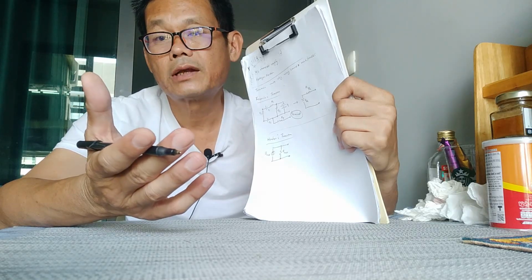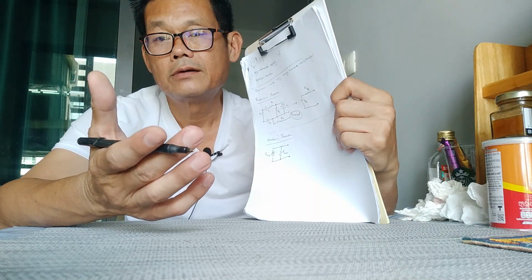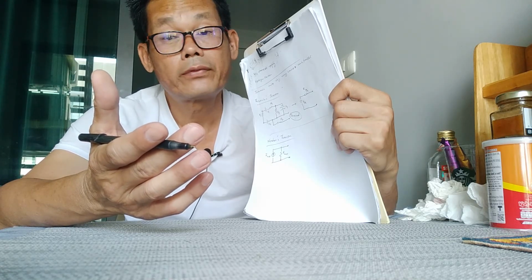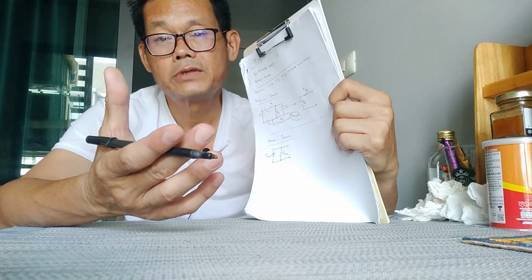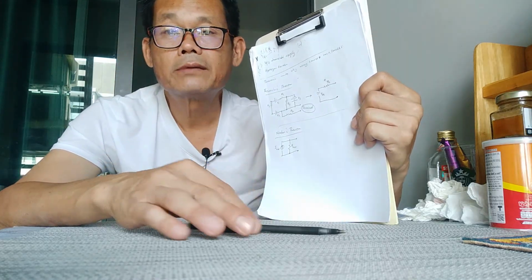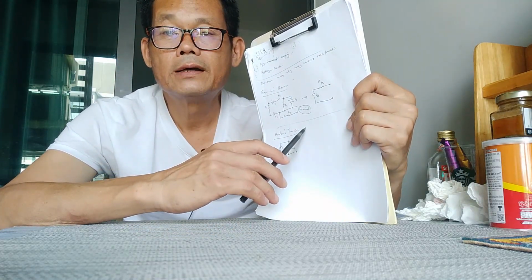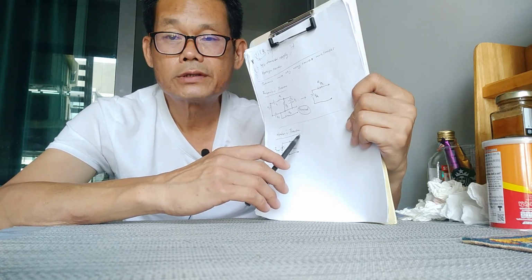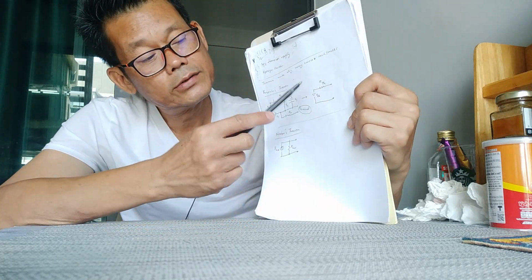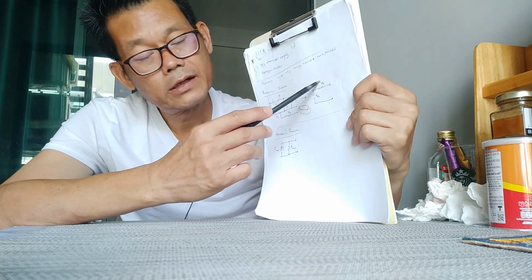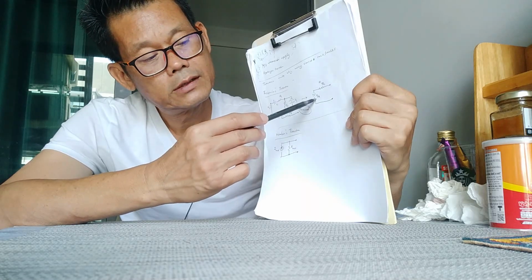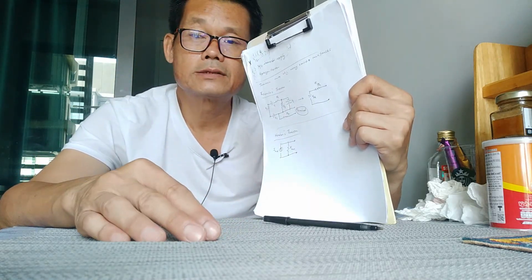And for the voltage, you measure by connecting your multimeter in parallel with the terminal, which has a resistor there. So you're going to have both V open and I short, and then you can look for RTH. Pick up a resistor that has a resistance equal to RTH, and you can apply VTH as the V open.